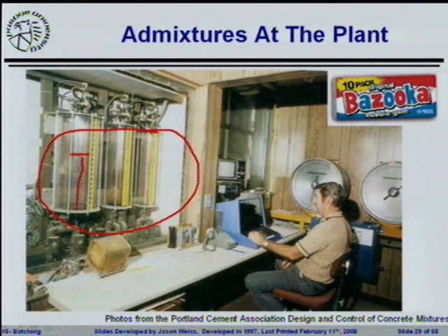One of the problems that you can get into, especially when these materials start to freeze in the late season or in the winter, is that their liquids, their fluids, and the systems could freeze. You want to make sure they're being batched out. Another thing that you want to watch out for is gumming. The valves on here, if you start getting a lot of evaporation or slow leaks at the valves, they can gum up and they can stick open or closed. And you want to have a good idea of whether the materials are actually getting added to the back of the truck or not. So this is one of the reasons why these are inside.